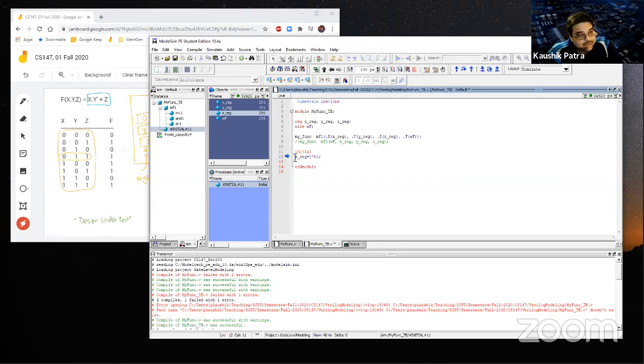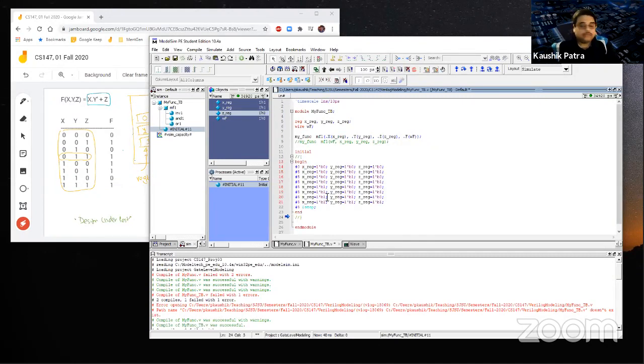Okay, but it can only cater one Verilog statement without a block. This is a one-liner statement, but as soon as you want to include multiple Verilog statements under one specific block, like initial, there is another block called always. There is another block that a switch case statement can have, a block of code. For those things, you need to define a block of code, which always has to be between begin and end.